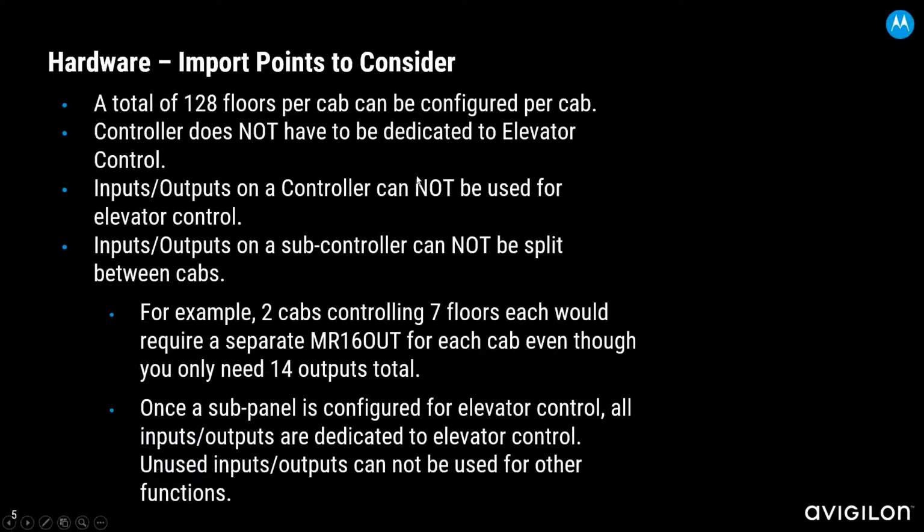Important points to consider when you're talking about elevator control. First thing is we can control up to 128 floors per cab, and that's assuming that you're using 8 MR16 output modules.